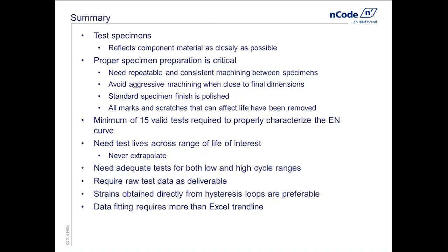I want to control the final surface finish on the specimen. And when we say polished, it's not like a mirror where I see myself in the specimen, but we want to eliminate any machine marks and scratches that would be initiation points for cracks.